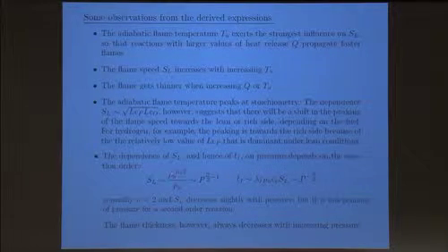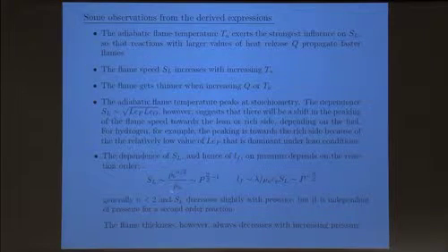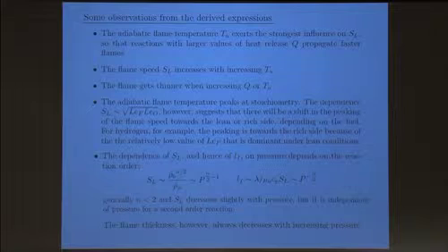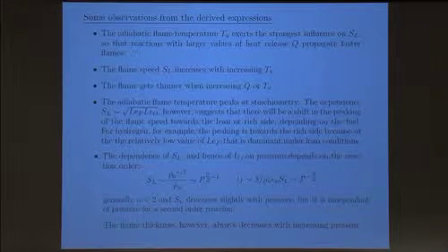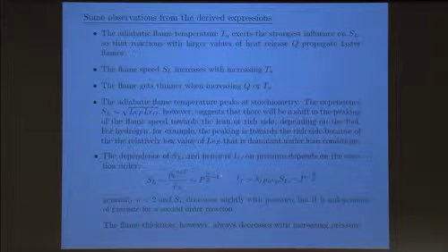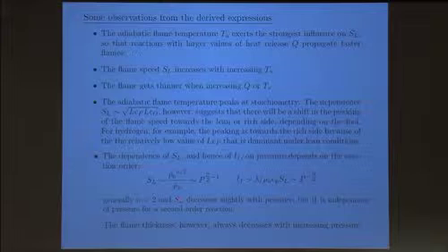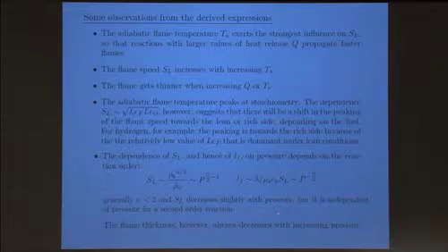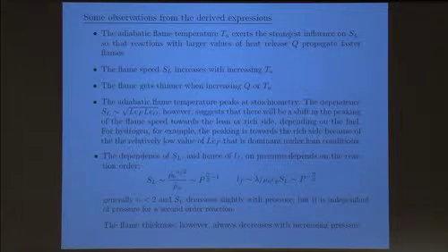So this gives you a pressure to the power n/2 minus 1 that comes from rho because of the equation of state, right? And so what you see, therefore, is that if the reaction order is less than 2, then the flame speed will decrease with pressure, and most reactions have overall reaction order less than 2.